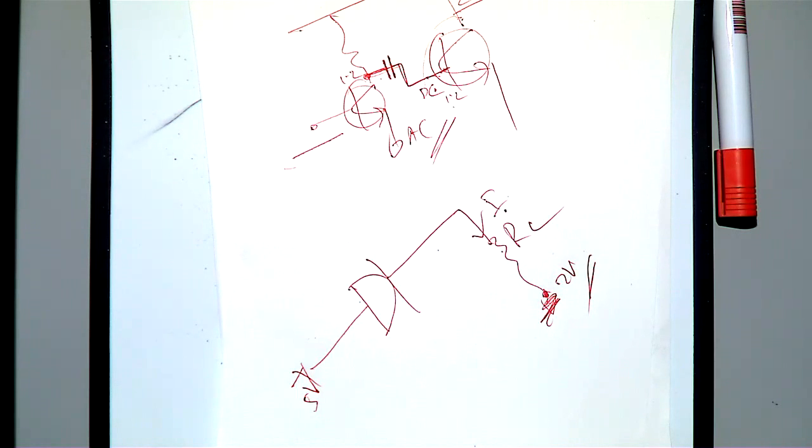Otherwise what will happen is, you have this issue. When this voltage is 1.3, then you need more voltage here, because only then will this transistor be on. When you have a couple of stages, this base voltage requirement will become close to 10 volt, then you don't get much voltage swing. In order to avoid that, you can approach two ways. You can connect a level shifter maybe in between, you can shift the voltage, or you can use a PNP amplifier with a voltage level shifter. So PNP you can use, then you get voltage level shifting. You don't have that effect.